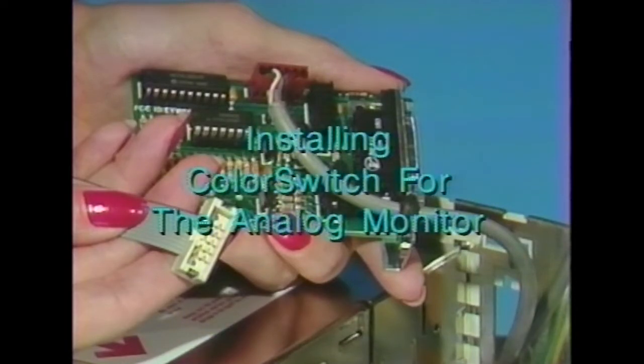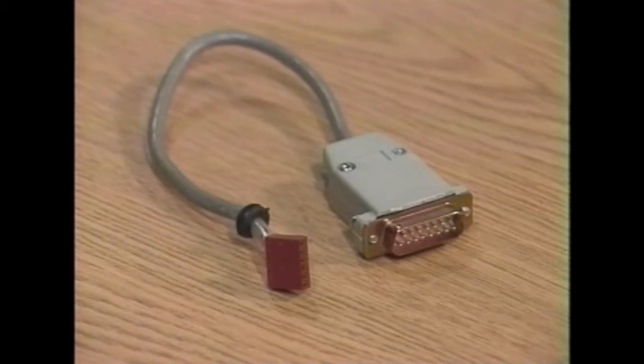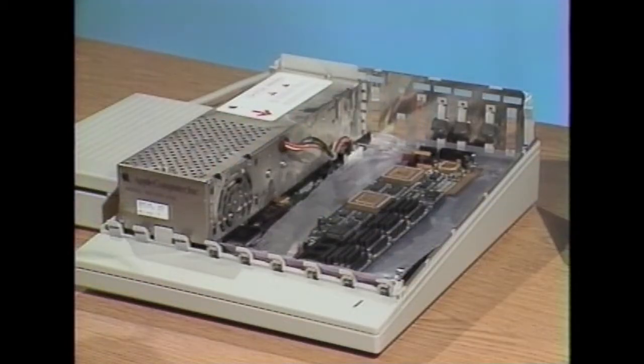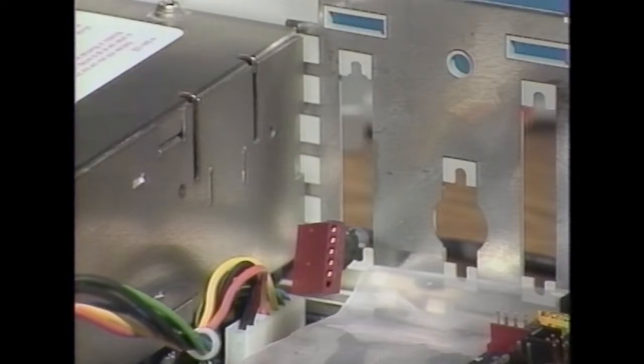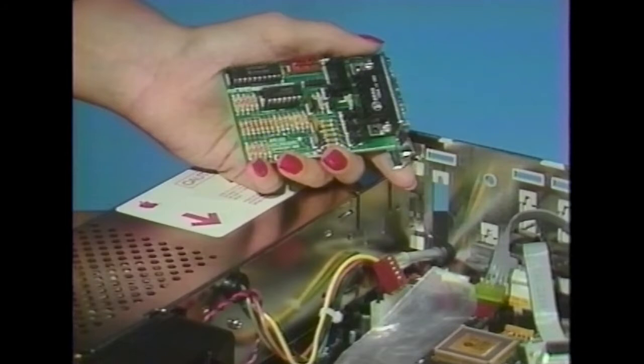Installing color switch for the analog monitor. To install the color switch, first locate the RGB adapter cable. It looks like this. Remember, the cable may have a slightly different appearance, but its installation and function will be the same. Feed the female connector into the opening in the back panel that is immediately next to the 2GS power supply as shown. Now get the color switch card. Attach the female connector of the adapter cable to its male mate on the color switch, like so.